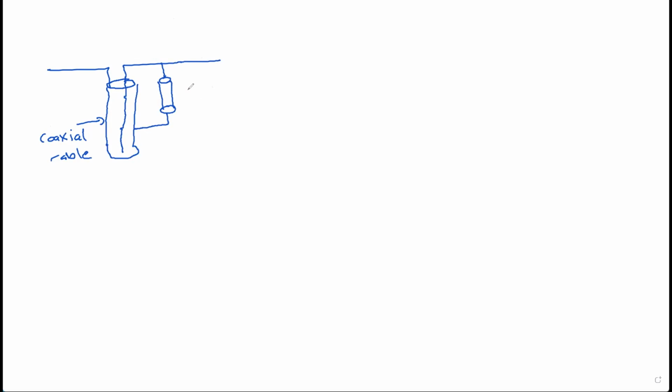The conducting wire is of length lambda over 4. We are specifically selecting a conducting cable of lambda over 4 in this scenario in order to obtain a specific impedance at the outer surface of the coaxial cable.